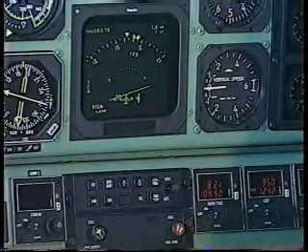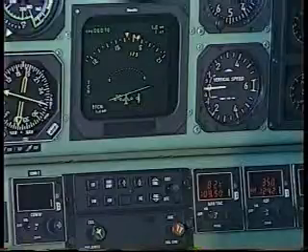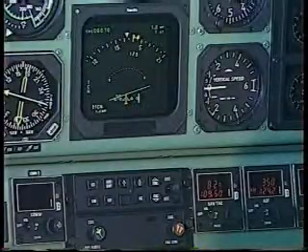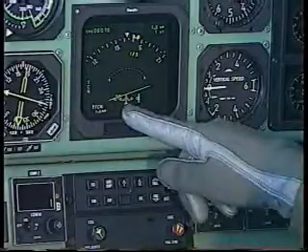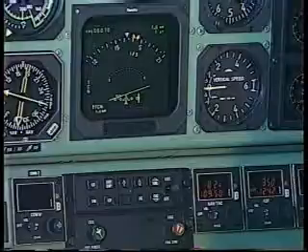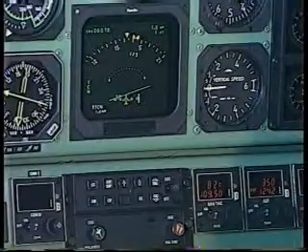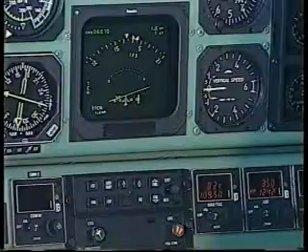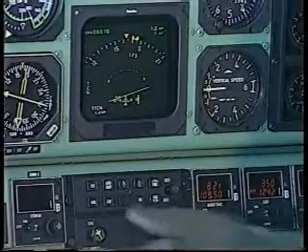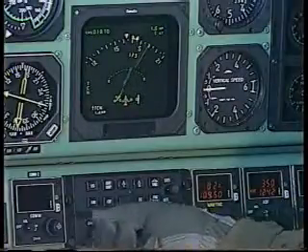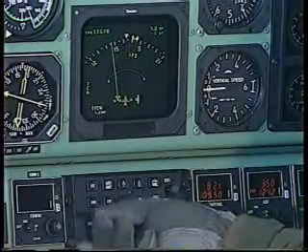This display is similar to the sector display from before, except that this time, the to-from annunciator above the aircraft symbol is replaced with a to-from near the course readout. The digital heading readout is also back. The limitation with MAP is that it's only useful for TACAN or VORTAC stations. It will not draw symbols for any other radio aids.